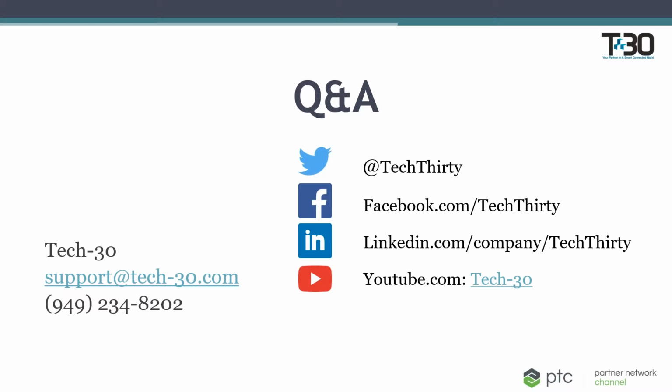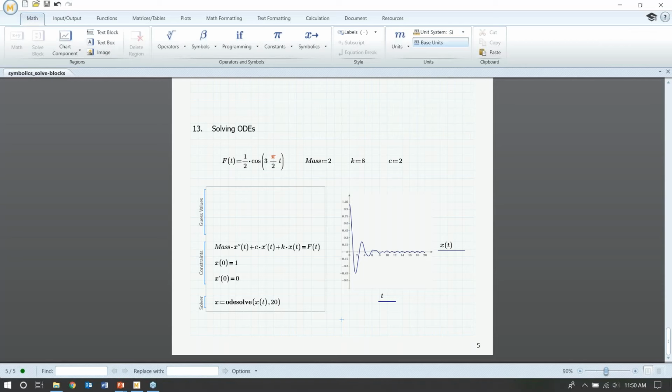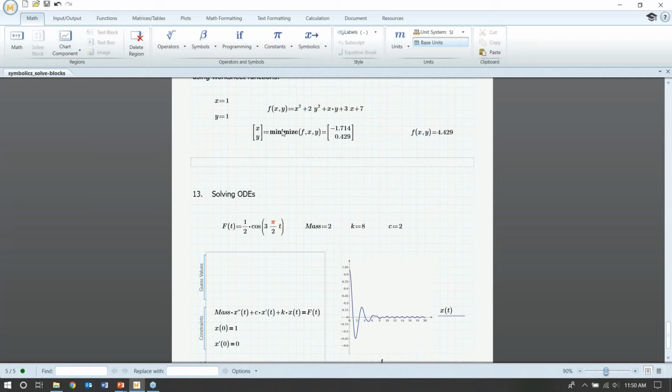Kuros followed up on his question about drawing. Can we add sketches? So let's say that he brings a picture into Mathcad and then wants to add arrows and dimensions and other annotations. Do you know of a way to do this currently in Mathcad Prime? No, I haven't seen any way to add arrows or anything on top of a picture. All we have is the text box, where I could just show you. We could add a text box or something, but there's not really a way to add arrows otherwise. I mean, you could do something like this. It's not really great, but that's the functionality we have in Mathcad for adding arrows or symbols.